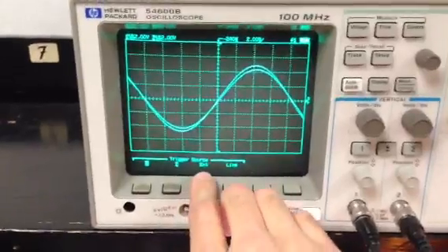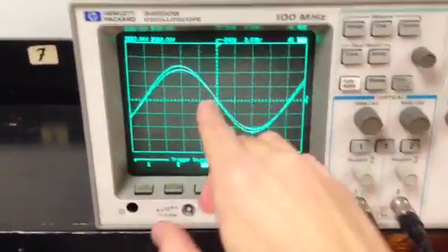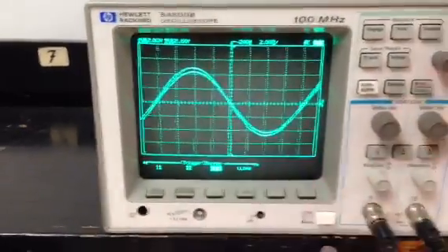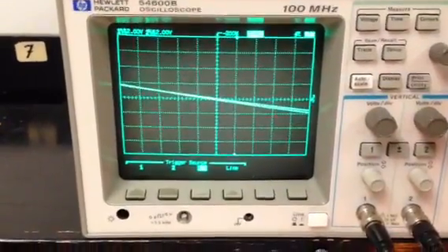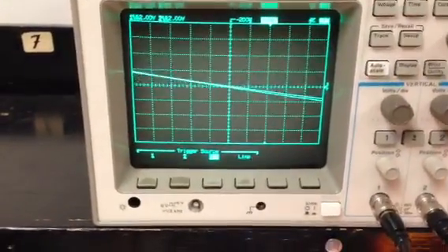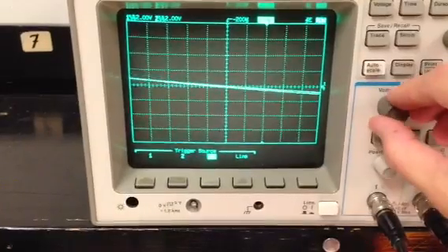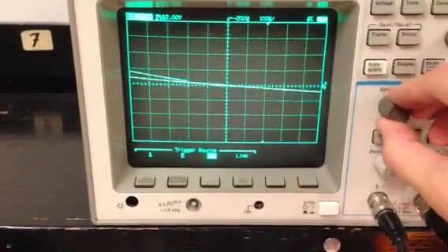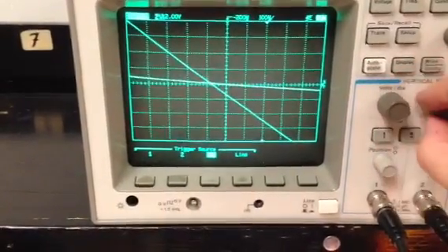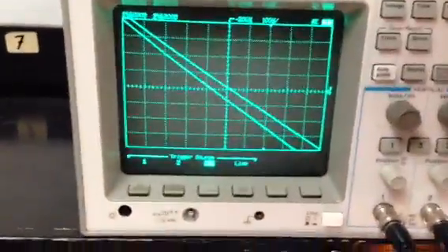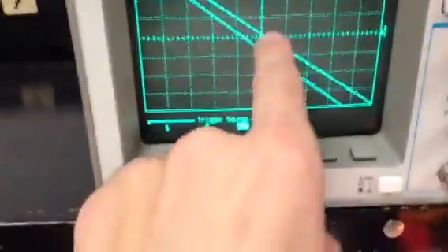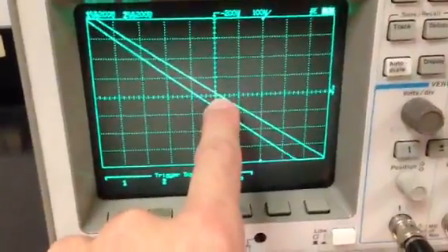I'm going to change it to external source. I'm going to put this as close as I can to 0. And now I'm going to zoom in. And it's still, oops, it's being a little flaky. Sometimes the voltage per division is a little flaky. So now we have our two waves here.